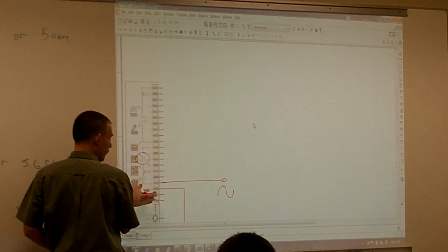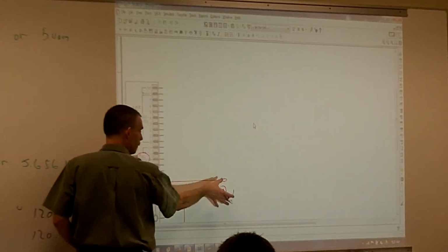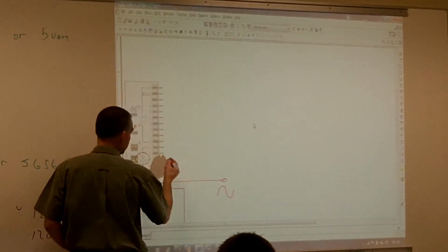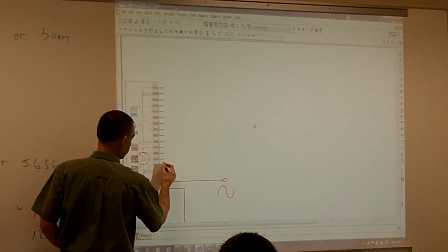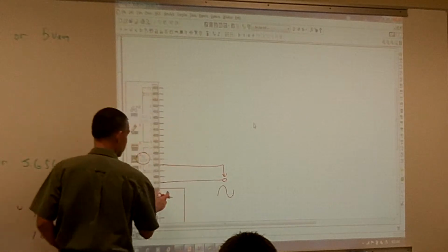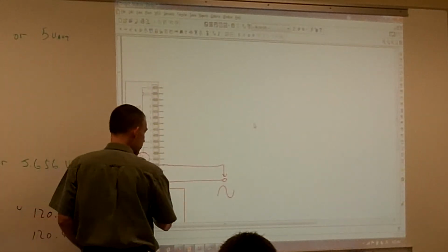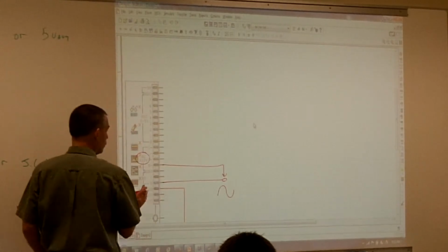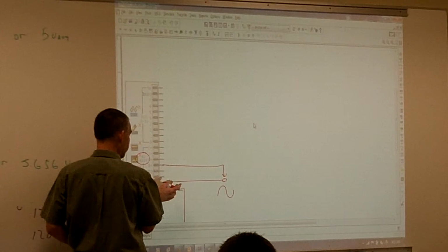So what I want to do is come off of my analog output, my channel 0, and measure this signal coming off of it. So I'm going to go off of my analog input, channel 0 plus, and I'm going to go right into my analog output, channel 0. Now I always need a reference point when I'm referencing a signal, my point of reference.